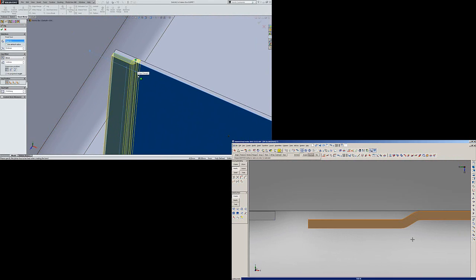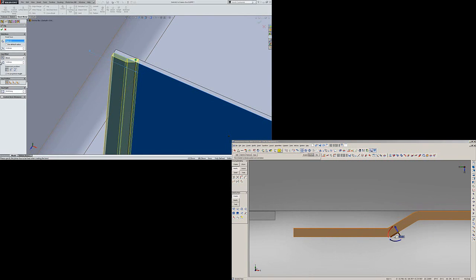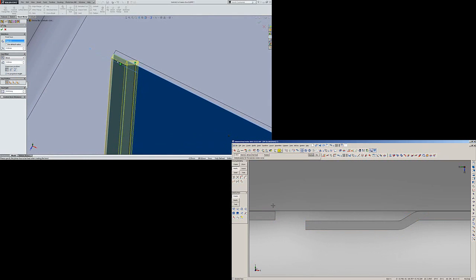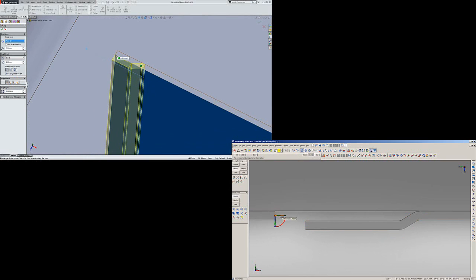That's not exactly possible with the angle at 90 degrees or 70 degrees as it is, so we're going to change that to 30 degrees, like that. Now we want our blind end condition to be at 1.6, which is correct. Now I just want to talk about this fixed projected length. That's projecting right to the end of the edge flange that we created earlier. If I deselect, it'll be more realistic that where that bend comes in, it's going to be a little bit shorter. So I want that checked, and I'm going to go ahead and OK those selections.